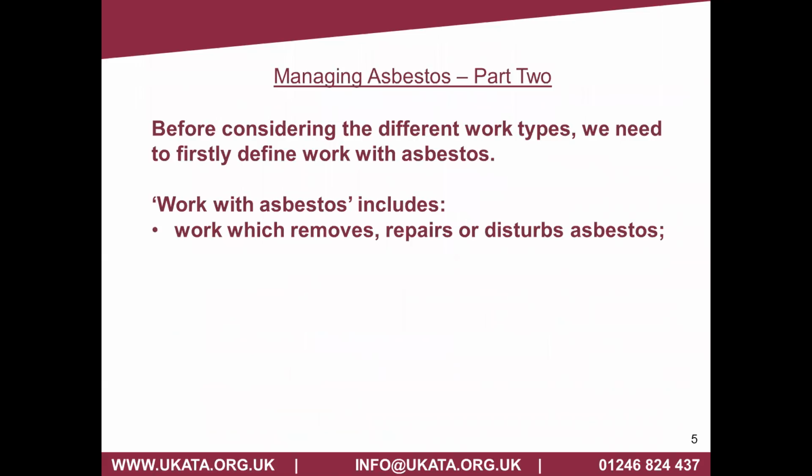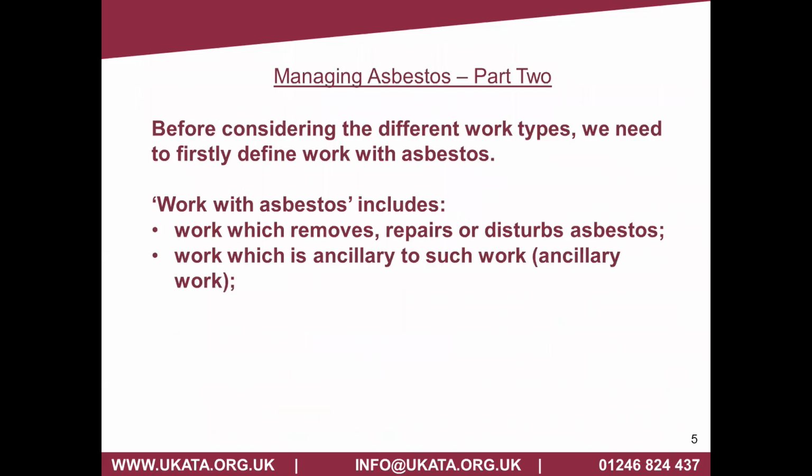Now, work as defined in the regulations, the Control of Asbestos Regulations L143, work with asbestos includes work which removes, repairs or disturbs asbestos. So a good example of that would be a contractor who is going to remove some asbestos roof sheets, or maybe drill holes in textured coatings or remove some floor tiles. That is all defined as working with asbestos.